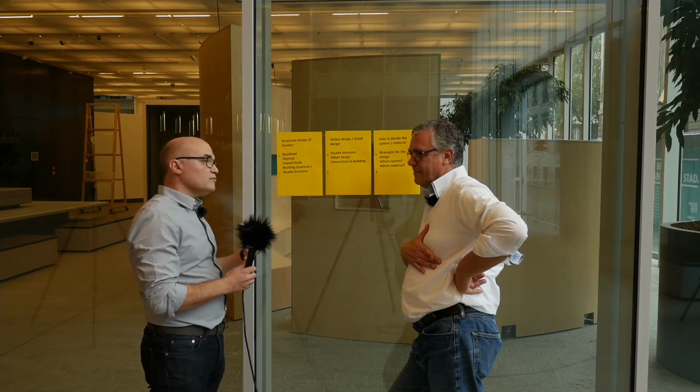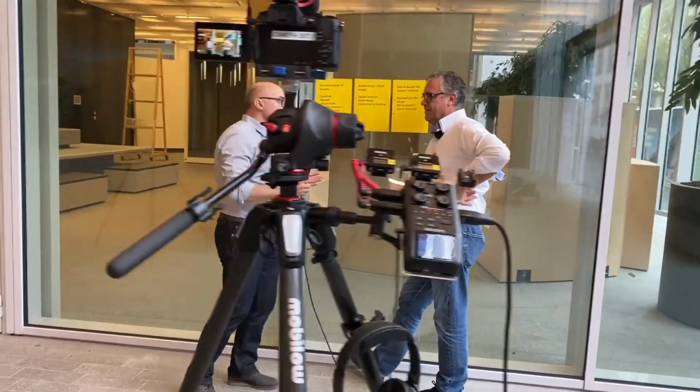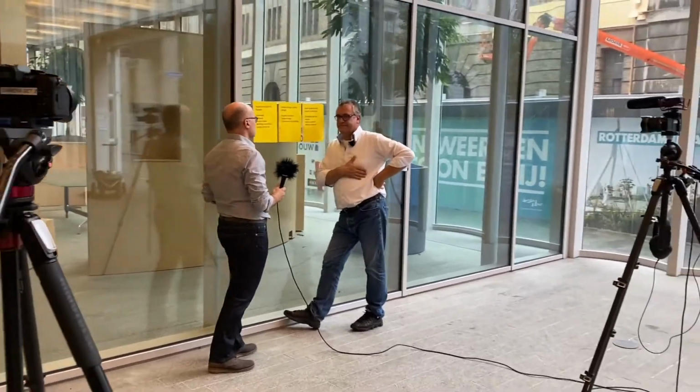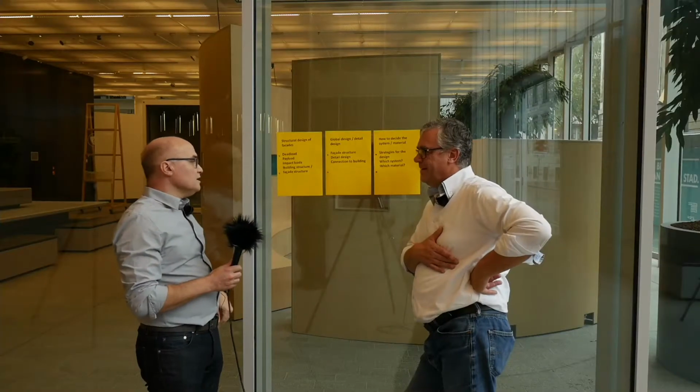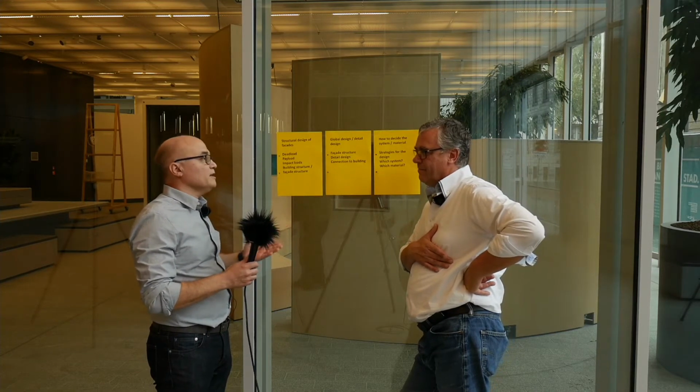Then apart from that, you also have horizontal loads from possible impact. So someone, with full height glazing on the third or fourth floor, stumbles and hits the facade from the inside. You don't want that person to fall out, clearly, so the facade must resist that impact. And then you also have hard body impacts from outside, perhaps through vandalism, maybe through maintenance, where if you put a ladder or you're using a cleaning cradle, you want your facade to resist that impact. And then there are other extreme loads. In some areas you might have a blast risk, maybe a risk of explosion. This is maybe quite specialist and quite extreme, but it is possible.